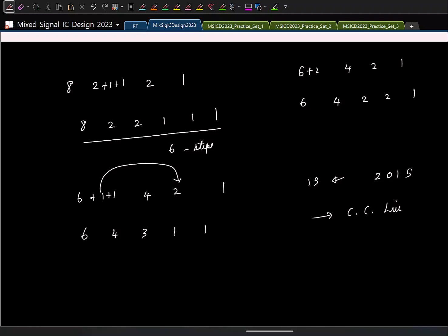And again, if you look at the timeline, the SAR, as I mentioned, has been known for several years. In 2005 to 2006 is when the asynchronous operation was introduced. And then it all exploded. The interest in SAR design exploded. In 2010, monotonic switching was introduced. And the scheme that I have shown for redundancy was introduced in 2015. So it's all actually quite recent.